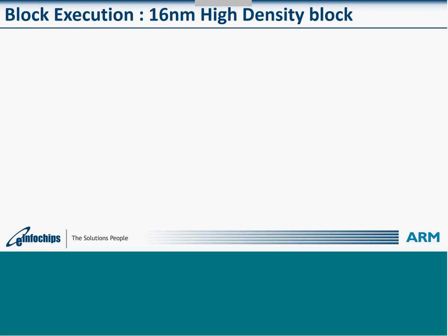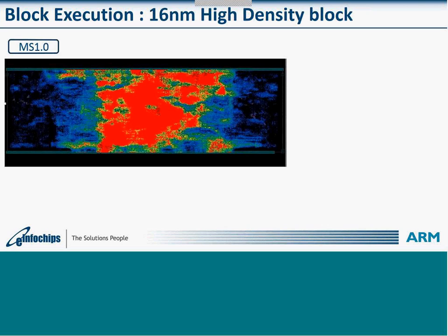This is one of the real life block execution challenges with 16 nanometer, a very high cell density block, where if one first goes, the entire red marks are really congested regions, and we have a lot of metal related issues here.